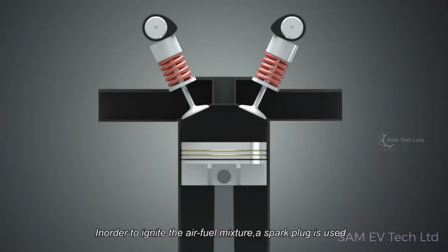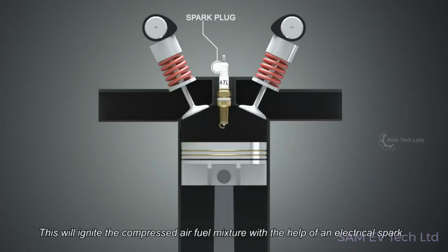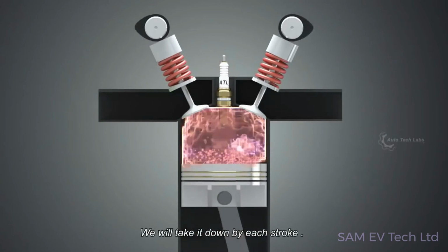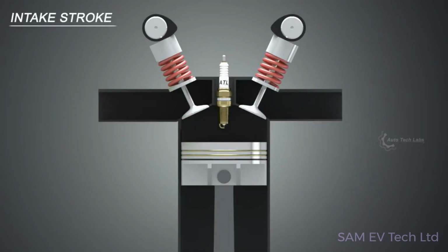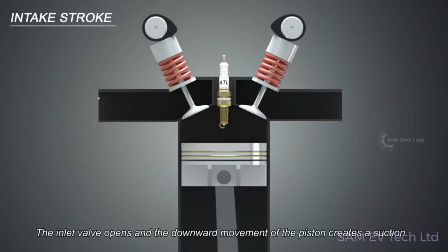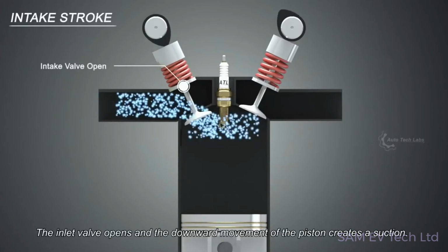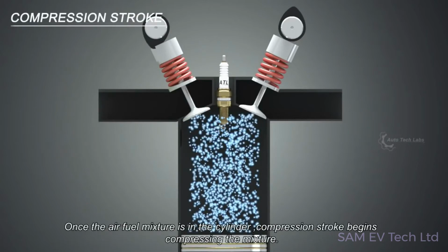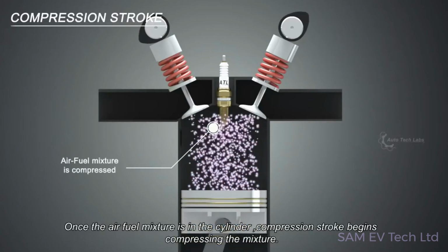In order to ignite the air-fuel mixture, a spark plug is used. This will ignite the compressed air-fuel mixture with the help of an electrical spark. We will take it down by each stroke. The intake stroke. The inlet valve opens and the downward movement of the piston creates a suction. This pulls the air-fuel mixture into the cylinder. Once the air-fuel mixture is in the cylinder, compression stroke begins, compressing the mixture.